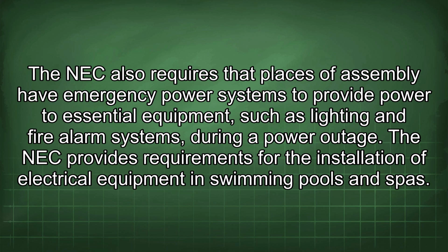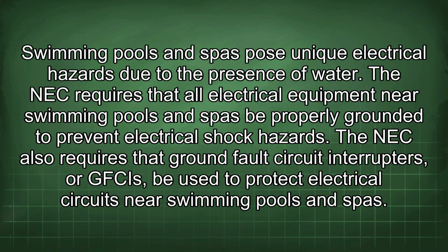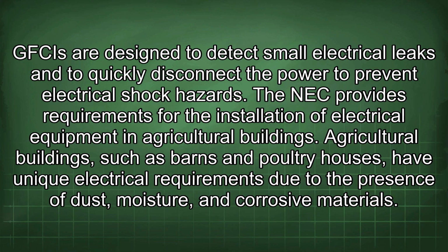The NEC provides requirements for the installation of electrical equipment in swimming pools and spas. Swimming pools and spas pose unique electrical hazards due to the presence of water. The NEC requires that all electrical equipment near swimming pools and spas be properly grounded to prevent electrical shock hazards. The NEC also requires that ground fault circuit interrupters, or GFCIs, be used to protect electrical circuits near swimming pools and spas. GFCIs are designed to detect small electrical leaks and to quickly disconnect the power to prevent electrical shock hazards.